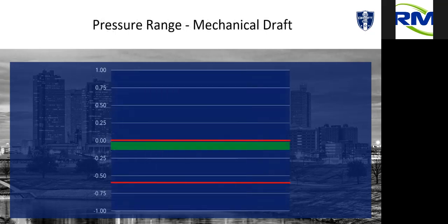Okay. And the other reason we do this, and the thing that really hits home is, we typically don't put a 105-degree thermometer on a 100-degree system. That's just not giving you enough of a range to see fluctuations in the system. So if your typical set point is, say, 0.05 to 0.10 negative, that doesn't really give you a lot of room on the high side. Now you have plenty of room on the bottom, right? But typically we aren't going more negative than what we're looking for. We're typically going more positive, okay? So there's not a lot of headroom here. With us, we can actually read about the same distance on either side of set point, and then we can react accordingly.